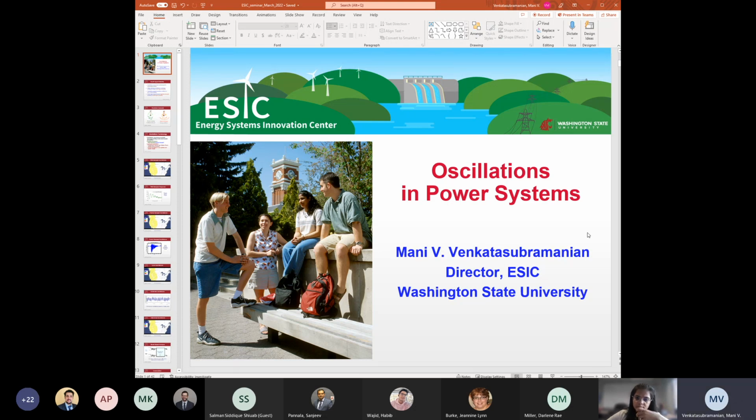And then in terms of real time, now we have these tools which are constantly monitoring the system, trying to predict when we approach problematic system conditions, and to develop operating procedures for if we end up in a poorly damped condition, can the operators maybe lower tie line flows or trip some generators to make the damping get better? And again, to design controls such as SVC modulation, HVDC modulation, to introduce damping or to improve the stability of modes, either as a planning study or as an operational tool.